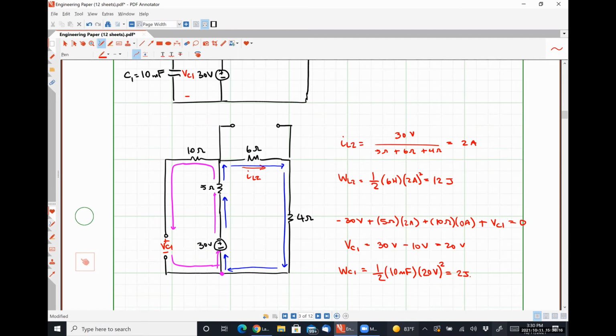Right, I understand that part, so I thought you had to do the negative. No. Well, no, so we're doing the, okay, because we're not taking the voltage. Okay, I understand what your question is there. So for a resistor, you're absolutely correct. If we have a resistor and the current is flowing into the negative polarity terminal of the resistor, then we do have to include a negative sign, but our source isn't a resistor, right?